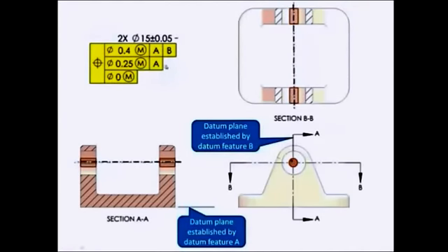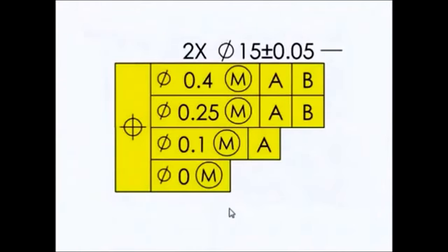In this third and final tip on composite position tolerancing, we will look at the effect of repeating the primary and secondary datum feature references in the lower segments of a composite tolerance. Whoa, you might think this is overkill of composite tolerancing, but we have had customers that required this level of control. Let's walk through it.